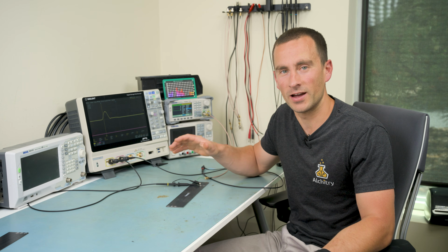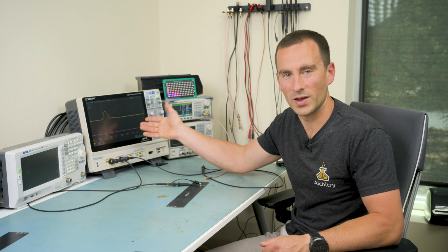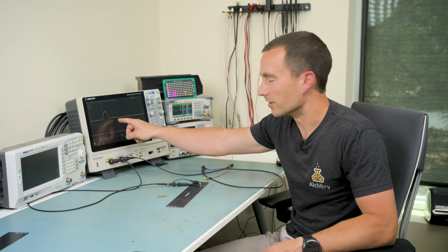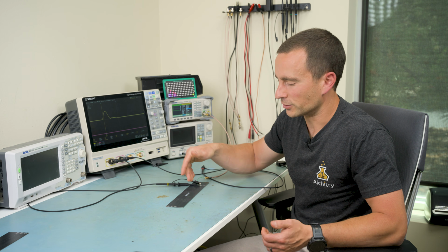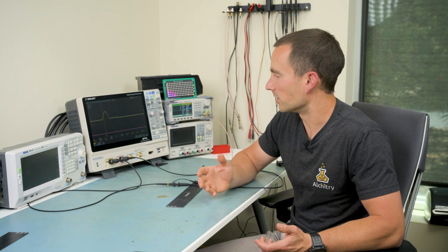All right, let's now take a look at the trace with a 49.9 ohm resistor on it. The reason for this weird value is that 50 ohms isn't a standard resistor value, but 49.9 ohms is. When we do this, we can see that we're getting basically no reflections. We have a little bit of a bump here. That's probably due to the trace not being exactly 50 ohms, but it's pretty negligible.